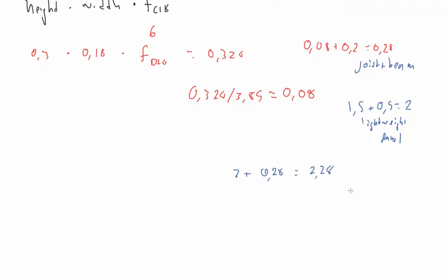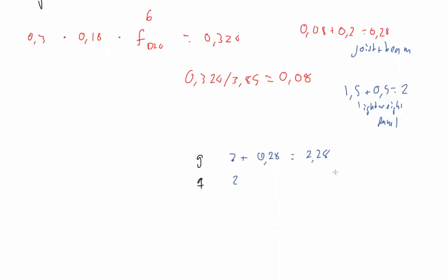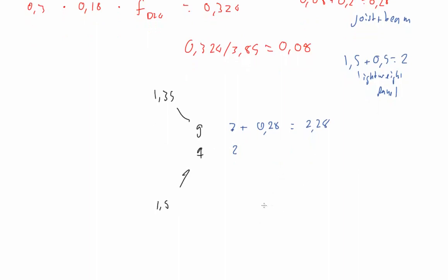This is the pure value, without safety factors. And also what I said before about the single family house, that's the live load. It spells live, but they say leave, I have no idea. That would be 2, right? The dead load is G, and this is the Q. The Q is for the live load. The safety factor for Q is 1.5, and for G is 1.35.